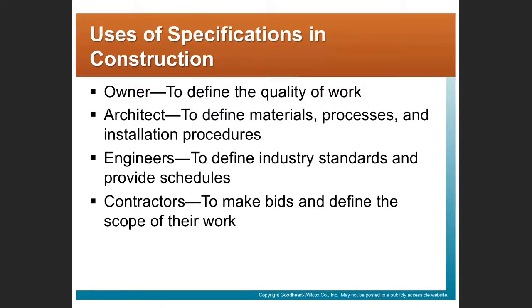So the architect in the specification is going to define the materials and the processes and procedures and the quality that they expect to have in the project. Again, the engineers, the electrical engineer, the mechanical, the structural engineer, they're going to typically define the standards that will be followed, and the specifications will often have supplemental information that's not contained on the drawings.